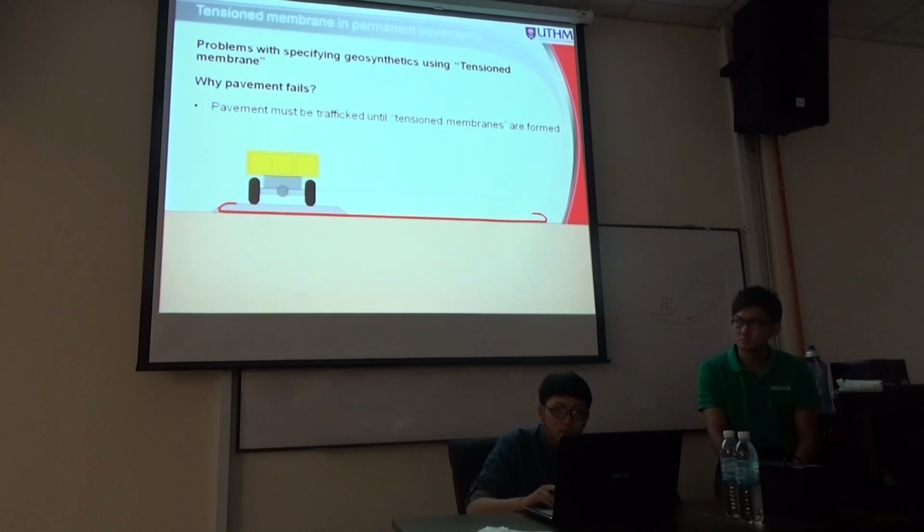So this red color one is representing the geosynthetic material with the strength, and they start placing those granular materials. They use a lorry to move up and down during the construction so that they can create this to achieve the required strength. Okay, so this one is under tension, they achieve the strength to support the lorry load good enough. The same is applied to the center part.